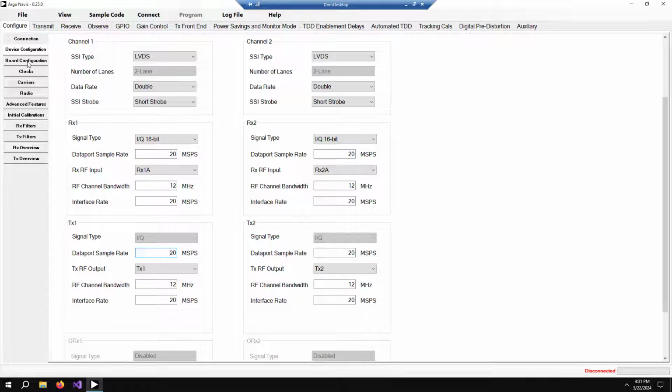There's a whole lot of things that you can do to configure the 9002 and put it in all sorts of different states. This software is just focused on the chip. So the eval board has certain firmware, it has certain device trees that we loaded. For instance, you remember we loaded the LVDS device tree.